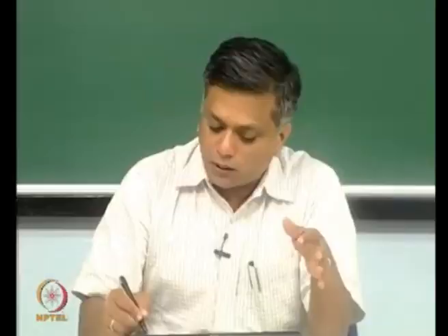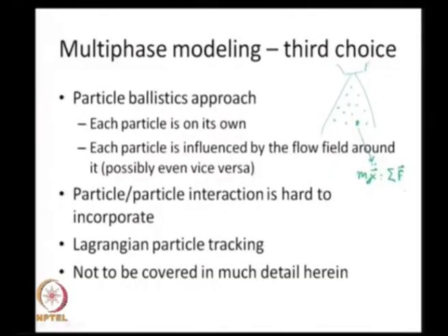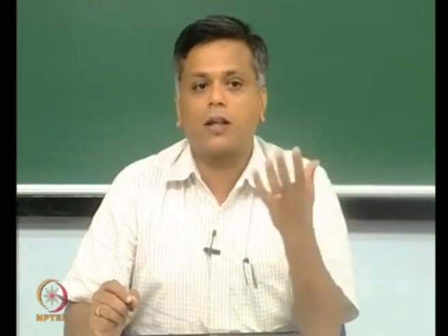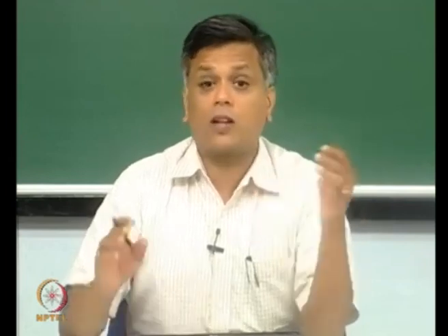What are all the forces that could act on this particle? One, the drag force from the surrounding air. Two, if there are other particles colliding with this particle and pushing it or creating an impulse force, creating any kind of additional force to accelerate or decelerate this one particle under consideration. Or I could have other external forces: gravity, some sort of an electromagnetic force if I am looking at other effects, etc.